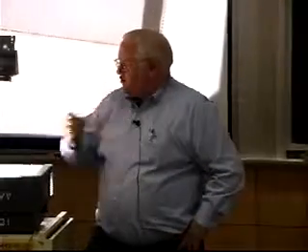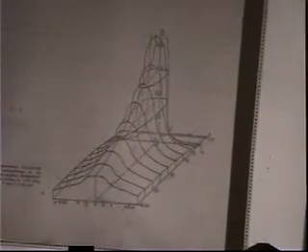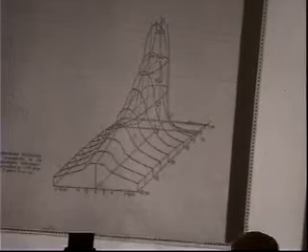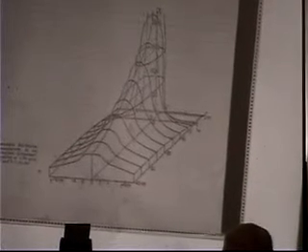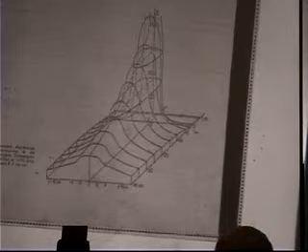But in any case, if you put the whole thing in dimensionless form, you end up with a plot that looks like this. This is the normalized dimensionless temperature distribution for any traveling point heat source on a plate, and it looks like a skewed Gaussian. In fact, if you look at it, that's kind of a three-dimensional view. This comes out of Christensen's paper.